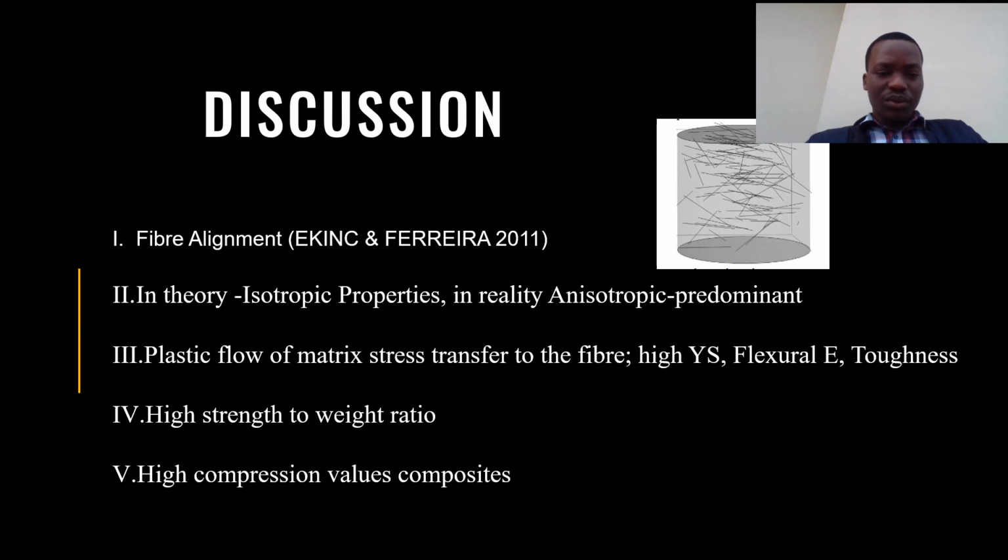There's a plastic flow of matrix stress transfer to the fiber, and this leads to high yield strength, flexural modulus and toughness. So this is the reason why composites have a higher flexural strength, toughness, as well as compression strengths. The fibers actually bear most of the load instead of the matrix, and this helps in improving the properties I've already mentioned compared to a pure material which is not reinforced.